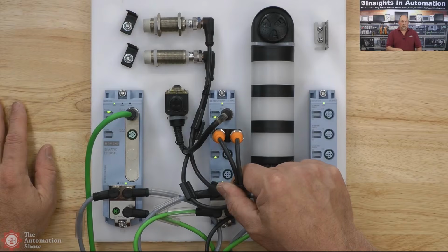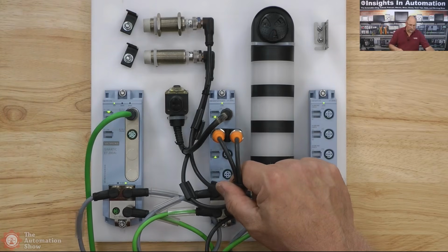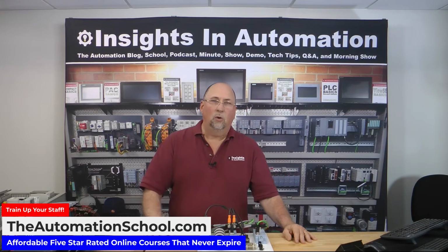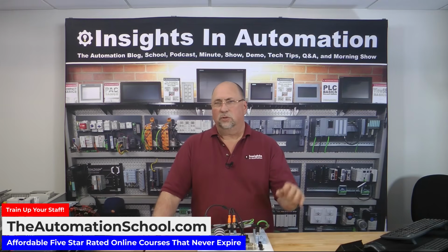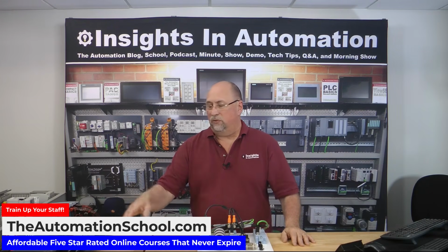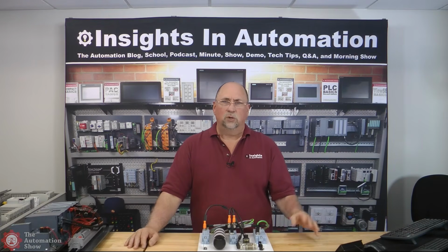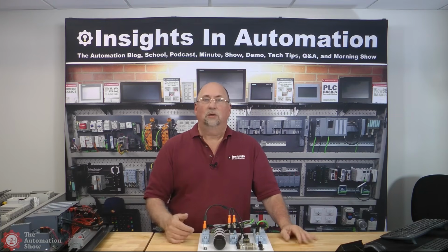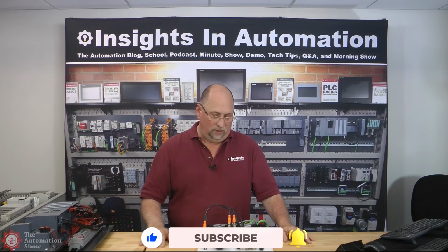Excellent. So that's how easy it is to integrate ET200 AL I/O into your S7 project using TIA Portal. Again, I used TIA Portal version 18 here, and I used an S7 1500, but it works. I actually did all the testing at home with an S7 1200. There's no difference in how it works, which I think is pretty amazing, right? Because that little inexpensive unit can handle distributed I/O, not as much, but can handle distributed I/O just like the larger, more expensive S7 1500.